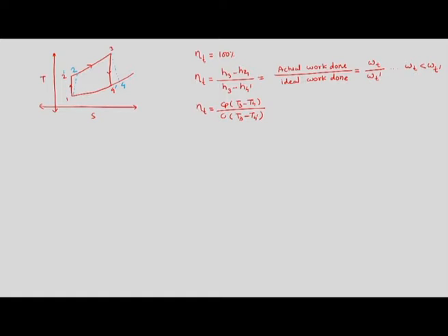The pressure at 4 dash and pressure at 4 is the same. Turbine exit is having the same pressure, whether it is ideal expansion or non-ideal expansion. So we have the expression for efficiency of turbine as (T3 minus T4) divided by (T3 minus T4 dash). Now for the process 3-4, the same thing we did for the earlier case.